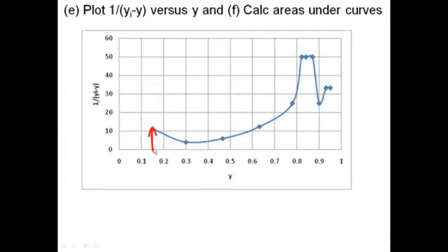The bottoms are going into the stripping, and then we switch from the stripping to the enriching at 0.8, and then the output from the enriching section is 0.95. So this section is the stripping, and this section is enriching.